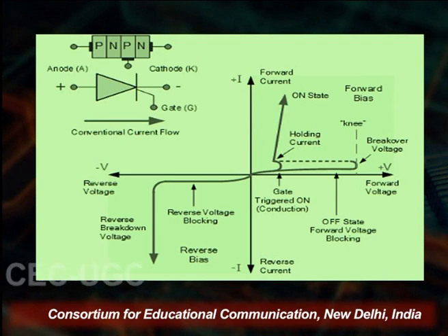When the anode is positive, the gate signal loses all control due to the regenerative latching action of the two internal transistors.